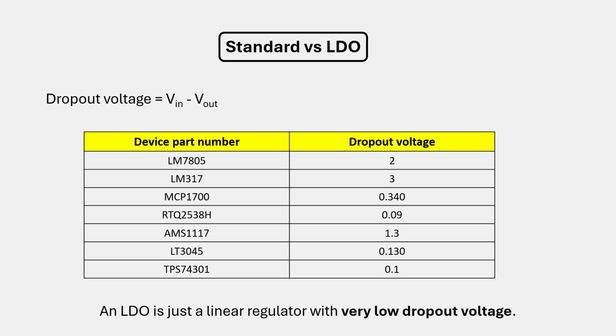But essentially, you're going to deal with it exactly the same as a standard linear regulator, with very few specifics involving stability, which we're going to take a look into. So, which begs the question, how low can it be in order to be considered an LDO? You're going to find lots of opinions and discussions, but basically that's a trivial question. We don't really need to have a definitive answer. But generally, people consider anything less than 1 volt of dropout voltage to be an LDO.